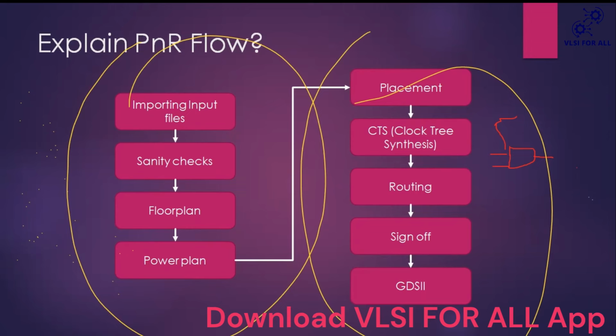During initial placement, it may not follow any DRCs; it will try to overlap standard cells or not align properly to the standard cell rows. After placing all the standard cells into the design, legalization will be performed by the tool.